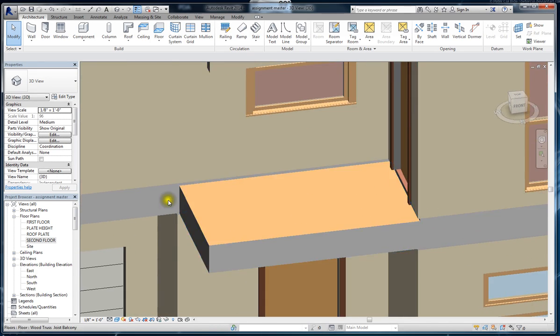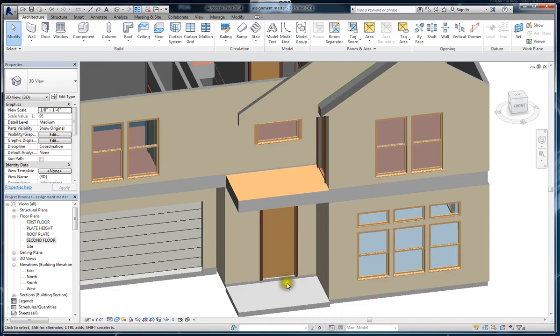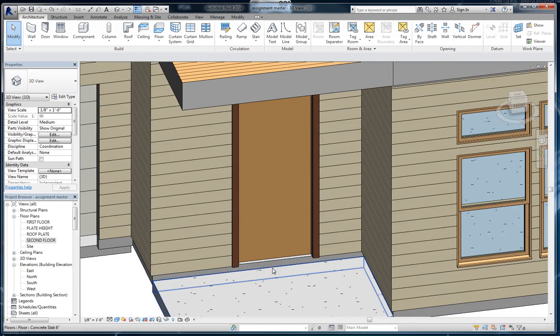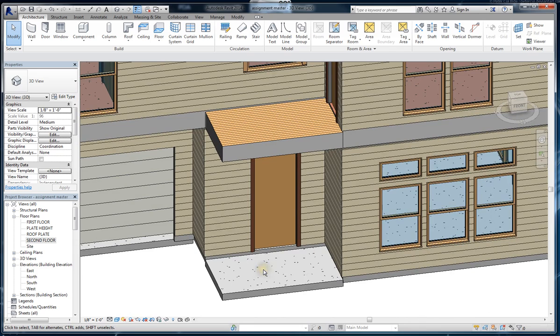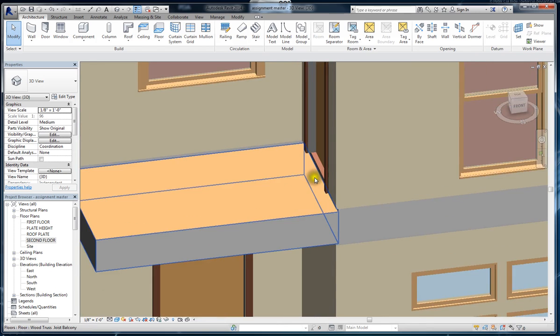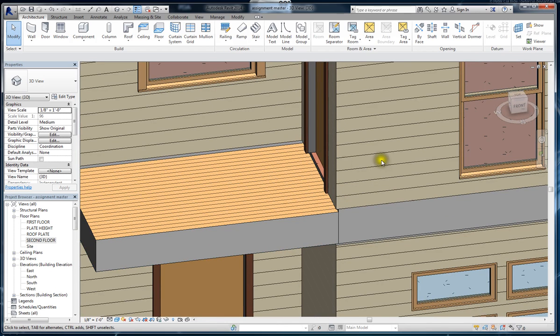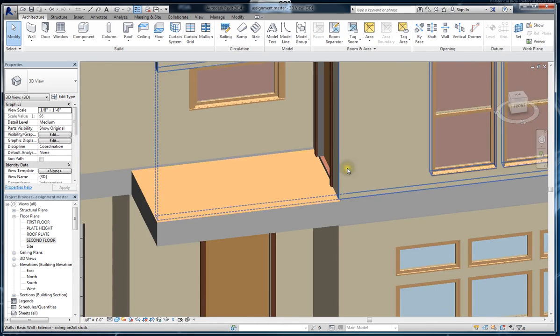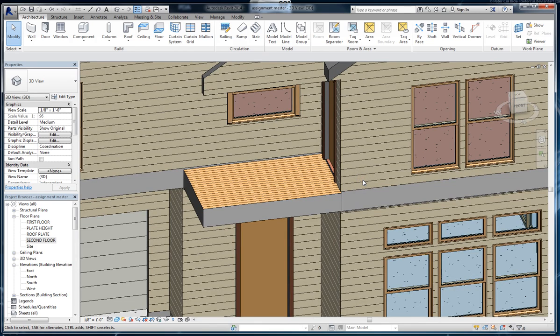So whenever you have a balcony, even the front porch, remember we went down 3.5 inches. So in a strong, heavy rain, if there's water being collected in the porch or in the balcony, water will need to travel up 3.5 inches in order to get inside the house. And on the second floor, it would have to travel up 2 inches to get inside the house. So you always want to have a step down at those front entry doors or door areas so that no water can come into your house.